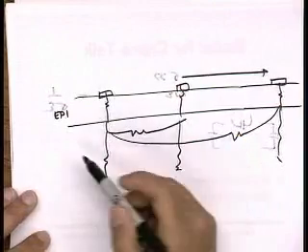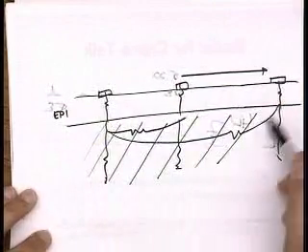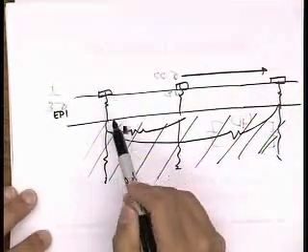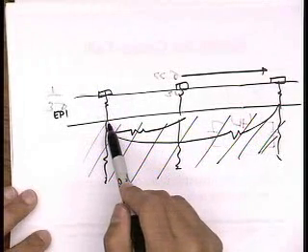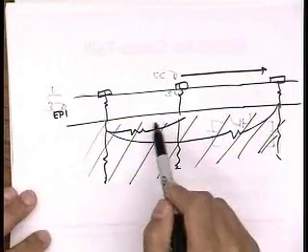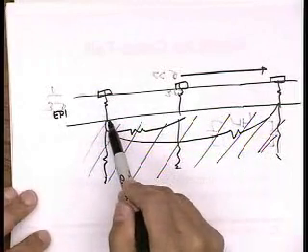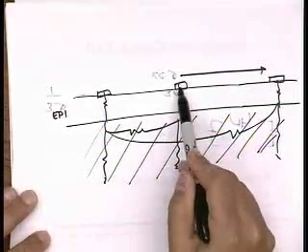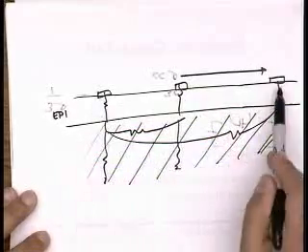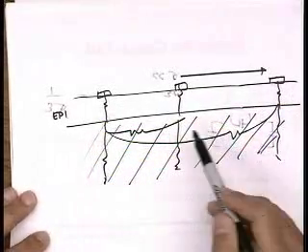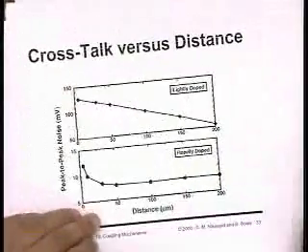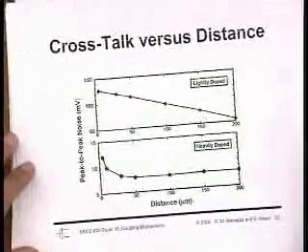Exactly. The way to think about it is this is almost a dead short. So really the resistance is dominated by the epi portion. So there's one resistance to go down, then almost a very small resistance, right? So let's just say 100 ohms, then like 2 ohms, and then another 100 ohms. And if I go way out here, I change like 2 ohms to 4 ohms, but who cares? That's a small fraction of the total. And that's borne out in measurements and more detailed simulations.